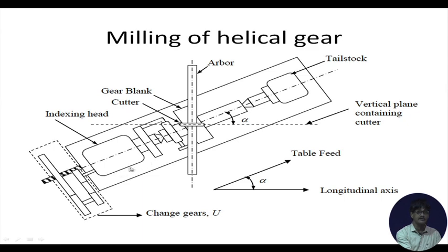The index plate has not been drawn here, but the index plate is here. The index plate is getting rotated. So, if we lock the index crank with the index plate, the index crank is also going to rotate, and this rotation will ultimately be transferred to the worm, and then to the worm gear, and then onto the workpiece.